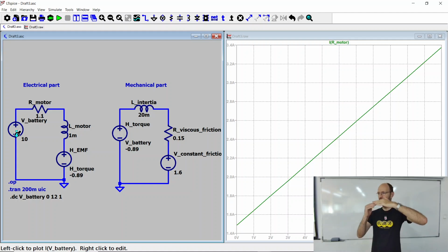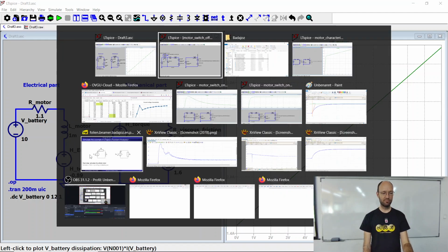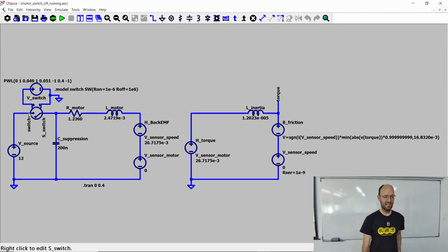But in my measurement, remember, I really switched off a switch, and I totally stopped and blocked the current. And so therefore, in my model, I really need to have the switch that switches off the source. Just setting the source to 0 won't do the job, because even if you turn the source to 0, there could still be a current through the source.